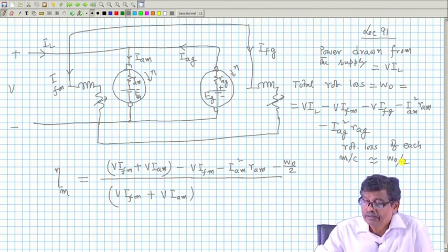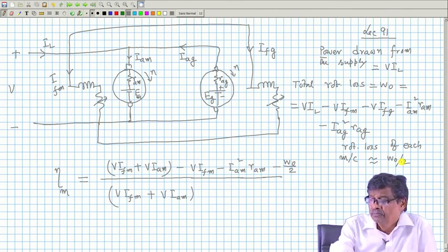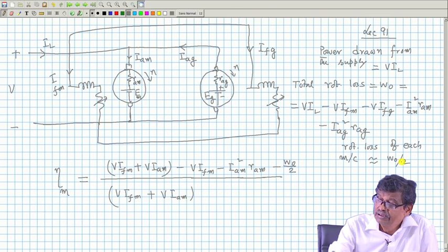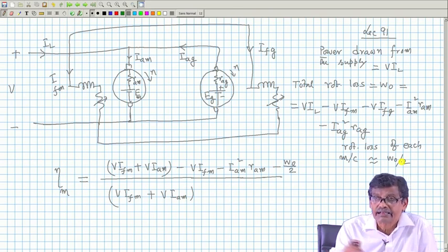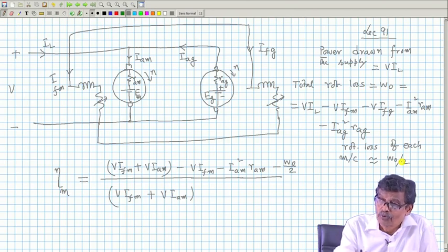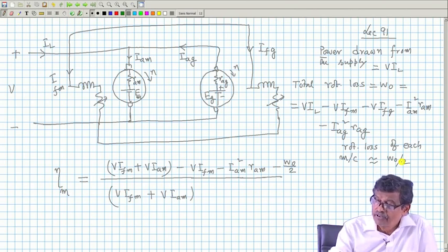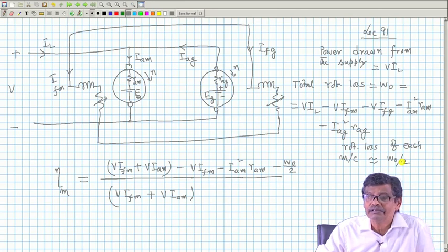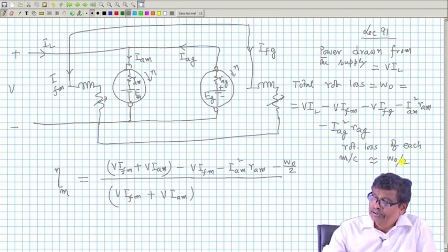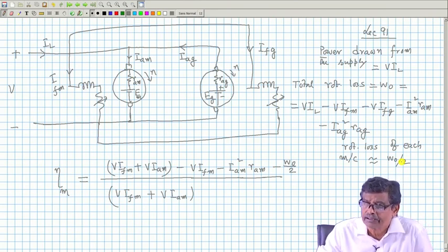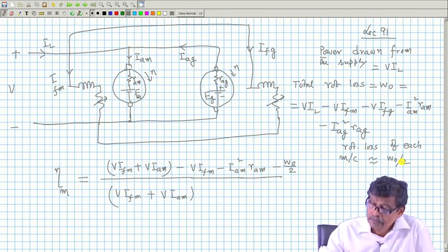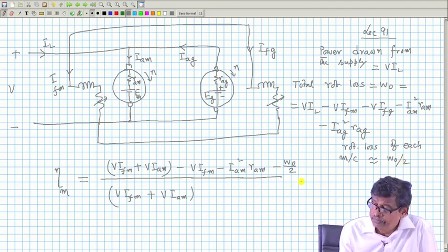Simply because, although this experiment is nice, you see the field current of the machine which is acting as a generator is greater than the field current of the motor. Therefore, flux level in both the machines is not the same, although speed is the same. But anyway, this is how I am estimating. So, this will be the efficiency of the motor, that is all.